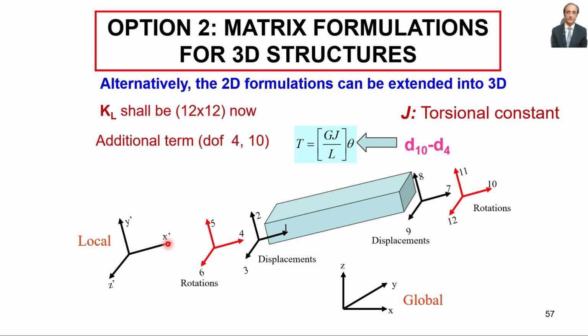For example, let us apply a force along the degree of freedom 2. So the member is bending, let's say like this. So this will generate a bending moment along the degree of freedom 6. Now the question is, which moment of inertia would be involved here? This particular moment is such that the moment of inertia along the local z-axis will be involved. So accordingly, the bending moment will be, let's say, 6EIz/L², if we are imposing the displacement such that all other degrees of freedom are locked.